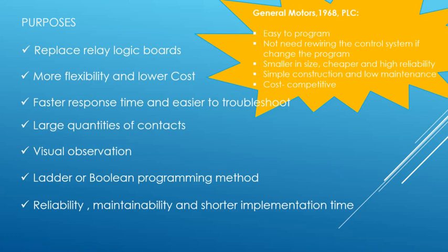And their system also takes a lot of space. Our system takes a very small place, and we implemented it in a short period of time. After we finished, both groups were able to do the same thing, with relay boards, relays and timers in their case, and a PLC with sensors in ours. Then he told us, okay, change the system to do this. And we were able to change that in a few minutes, because it was not really a big modification. However, the relay group took at least a week to modify, because they needed to rewire everything.